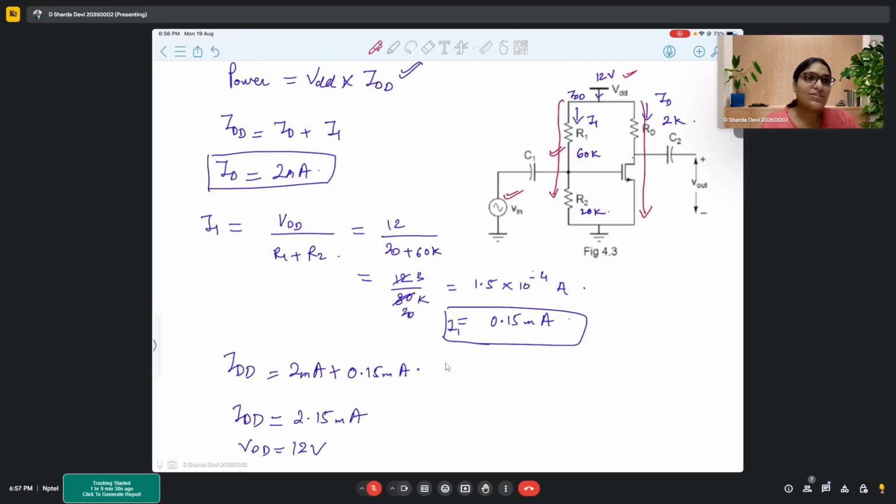So even in case of multi-stage amplifiers, what you do is you have one stage. The advantage that you basically get from multi-stage is not that your output increases too much. So देखो, if you have your VDD of 5 volts, your peak to peak voltage at output cannot go beyond 5 volts, right?